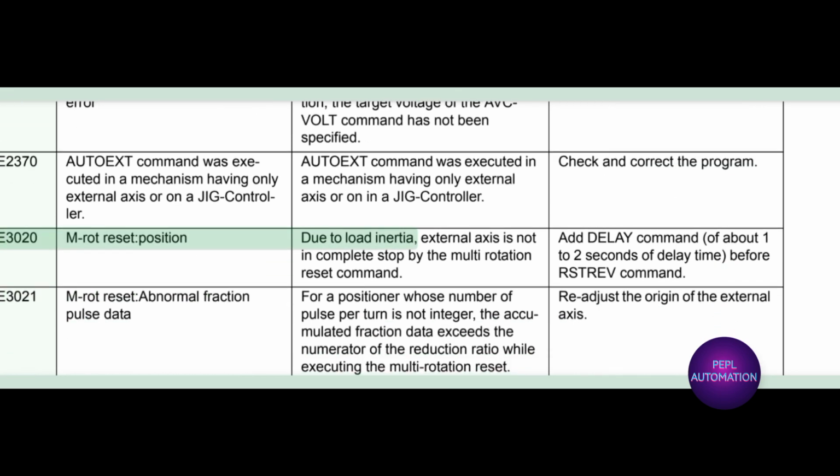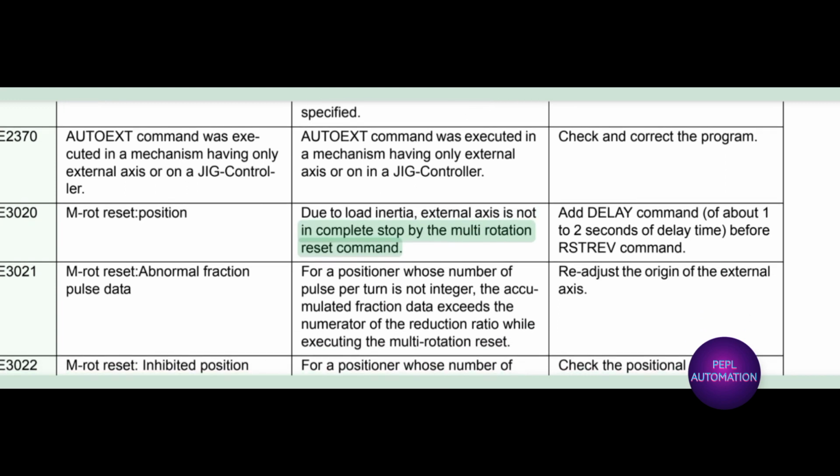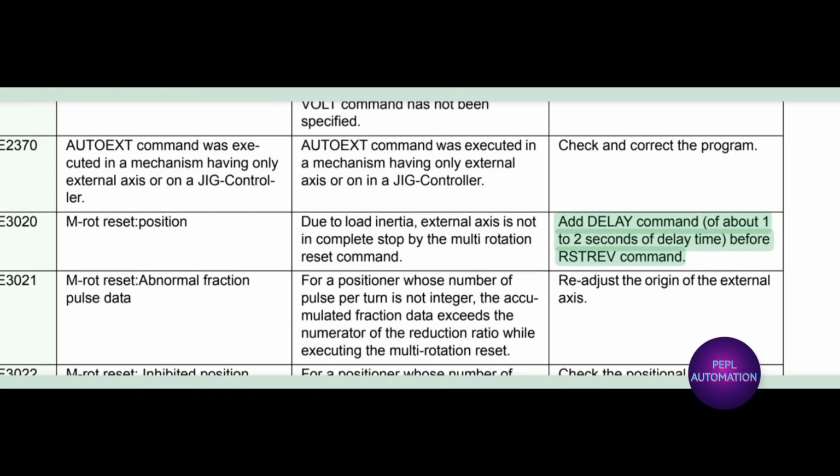E3020 lock reset, position due to load inertia, external axis is incomplete. Stop by the multi-rotation reset command. Add delay command, of about 1 to 2 seconds of delay time, before RSTREV command.